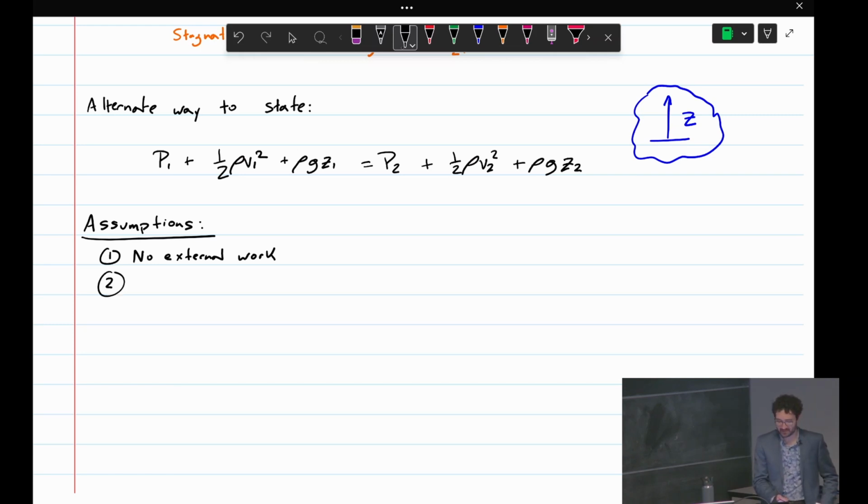Steady state. What does it mean if a flow is steady state? What does that mean about the three different types of lines we covered pre-midterm? They're all the same, right? If you put a smoke visualization in a field that's steady state, you automatically draw the streamlines as well. Normally the smoke visualization is a streak line.